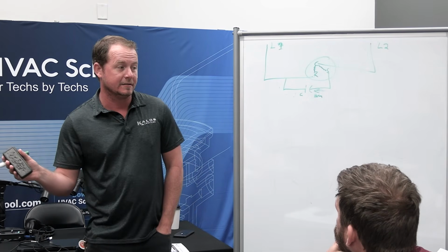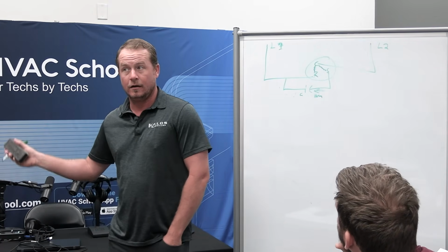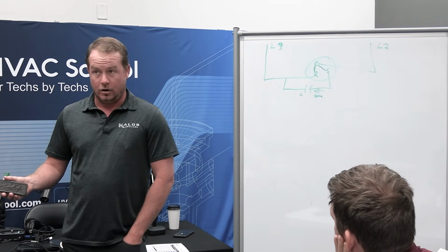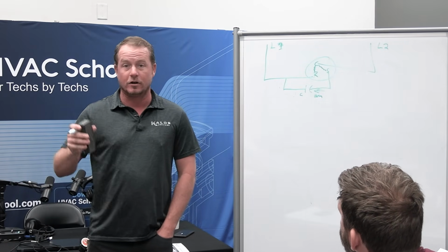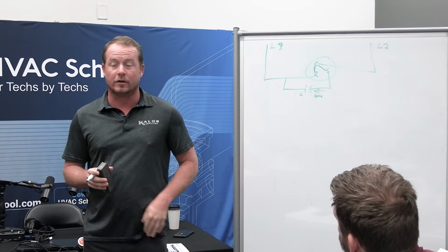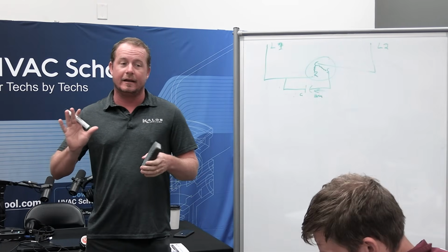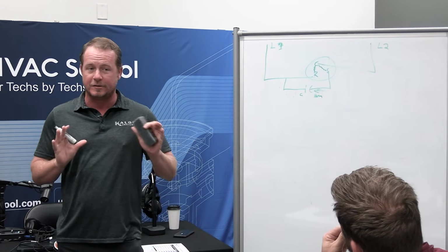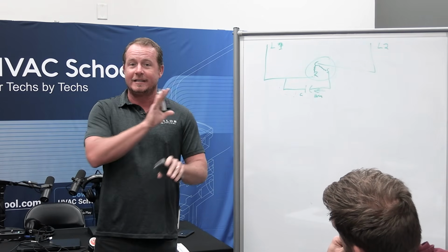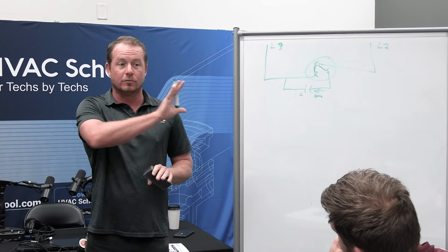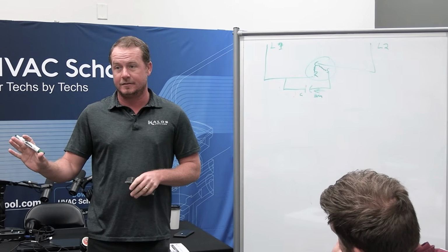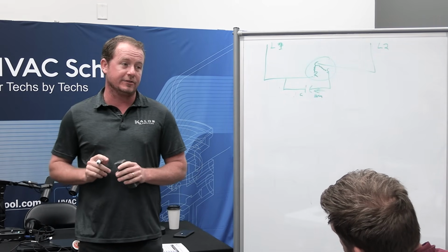What do you replace when you replace a compressor? Factory start gear, which would be hard start kit, capacitor, all that. Make sure, because in many cases, you may get a new replacement compressor that's a superseded compressor that might not actually take the same capacitor as the one that was in there. That happens. So you need to make sure the capacitor is the right size.